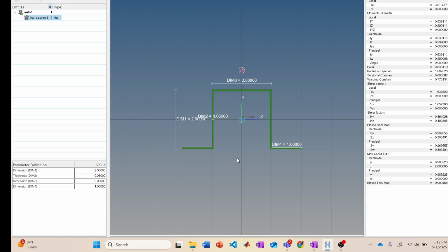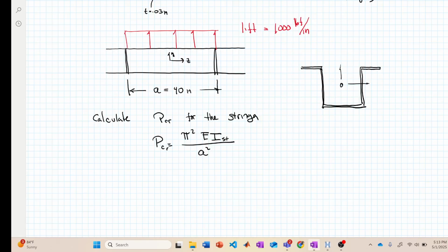So you can see that's the larger one, the 0.539, okay? And the centroid distance here is right in the middle, okay? I think that's all. I really need the area, and that IY, which again is IZZ, right? So, like I said, that's useful. I think you could draw your entire cross section in there as well and not use the spreadsheet that I have. I've never done that, but I'm sure that would work quite well.